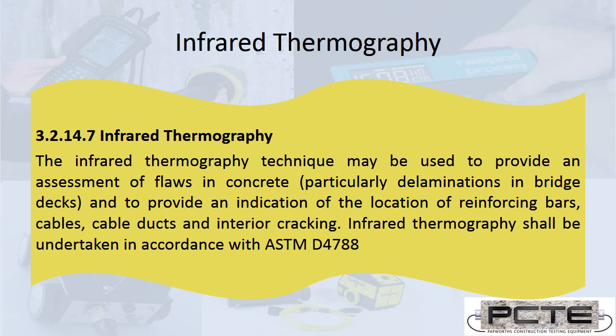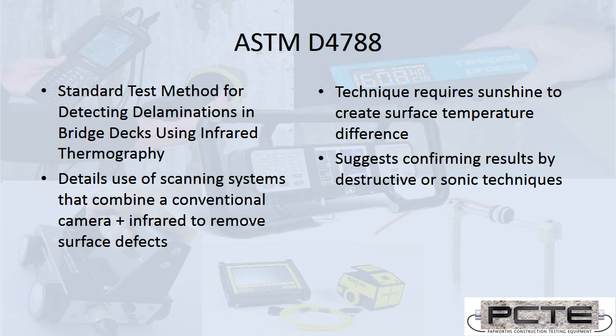And we're given an ASTM standard. The ASTM standard is specifically for a methodology to assess bridge decks or roads, concrete roads, where they are using video. So this is a video technique, recording a video of the area being measured and a thermal energy video of the area under test. So looking at both of these, it's possible to remove the influence of surface changes. So if you had an asphalt repair or something over a section of concrete, that would have a different heat. But because you've got video, you can subtract that from the final defect analysis.